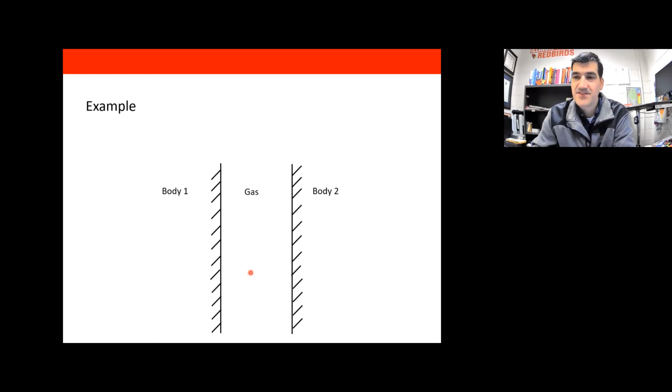So there's this compromise between having the gap too small, in which case your conduction thermal resistance will be small and you'll have greater heat transfer, and getting that gap too large, where you set up natural convection in here. So it's really quite a science to get the gap between the double pane windows just right, to make the thermal resistance from body 1 to body 2 as high as possible.